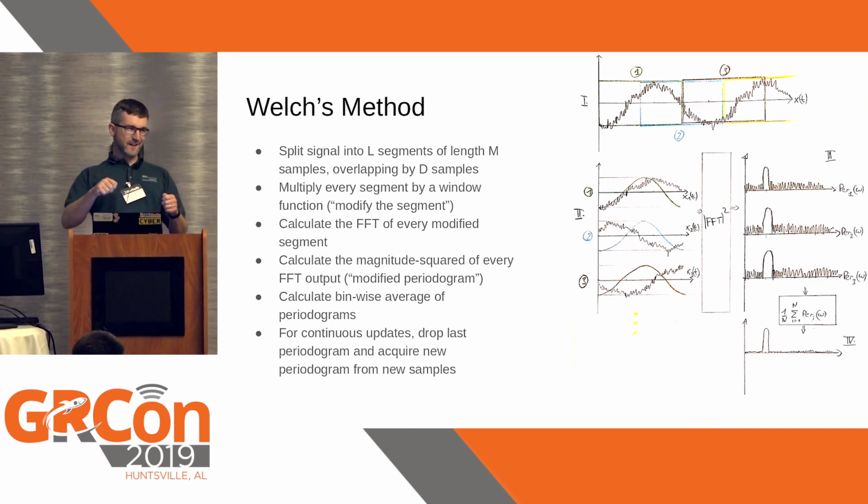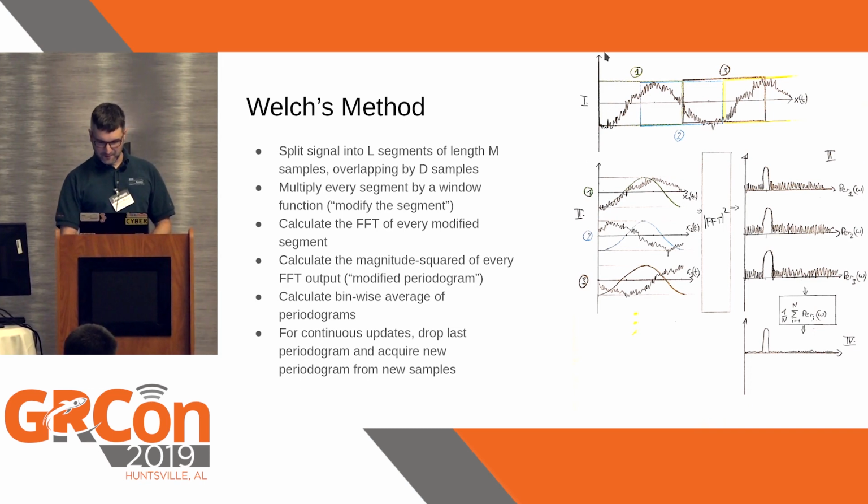I was sitting in the library. I didn't have fancy graphic tools, so I actually drew this by hand. So imagine you have a noisy signal. You can see I approximated a sine wave here. You split your signal into segments of time. Here they are. Take F of t's of that, and then the modulus squared of that. You get something like this. There's still plenty of noise here. And then you take as many of those as you like, average them, and then this would be your output.